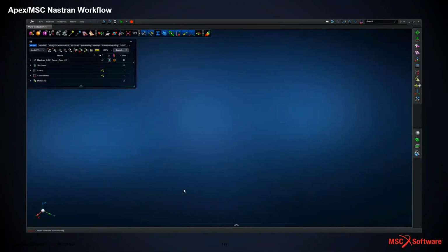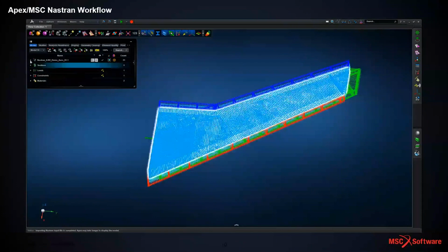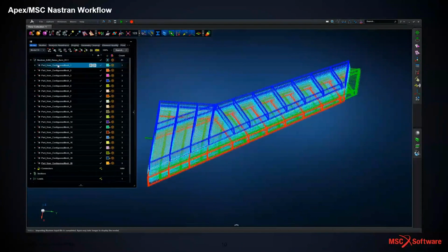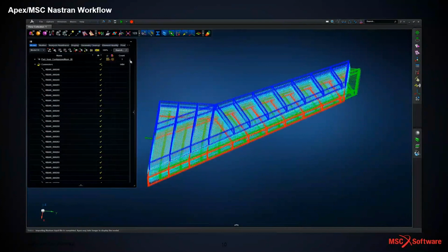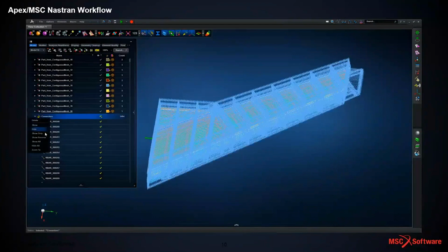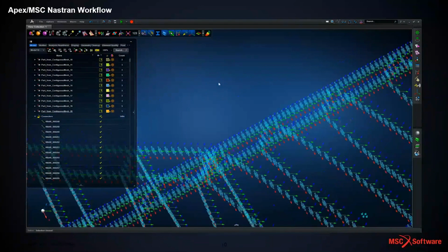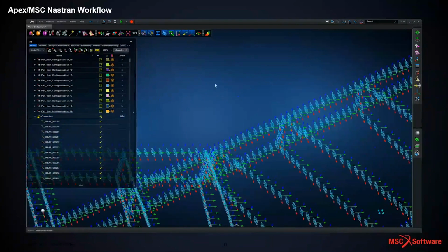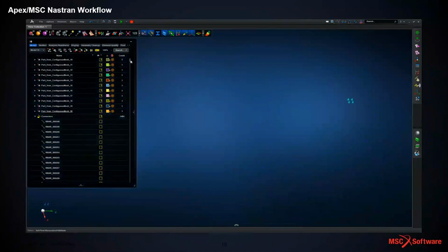the model. The model browser tree is populated with this model information, and then we can look in the tree and dig deep down into the product hierarchy, the structure in this case. So each part or sub-assembly is defined as a contiguous mesh region, and then we've got a number of fasteners which tie those parts together. In this example, we've got zero length R-bar connector types, and we can look at the coordinate frames developed for those if we were to use a C-bush or a fastener type explicitly.